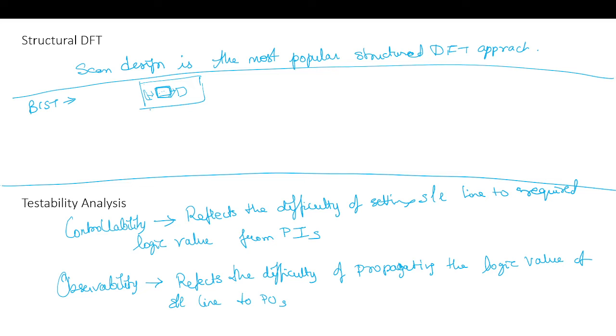For example, if it is a mobile phone, we just boot it, it applies some patterns, and it says whether it has a fault or not. So it is used for power-on self test, and mostly this is for in-field operation. When we have fabricated an IC, completely packaged, in the field, in operation, we perform the testing either at boot or whenever the system is idle.